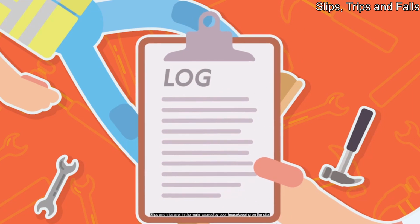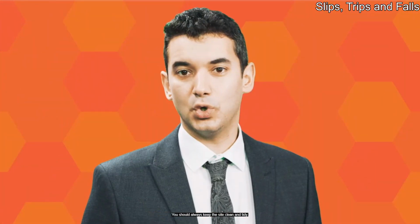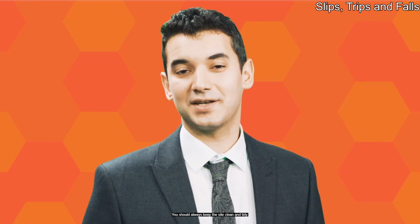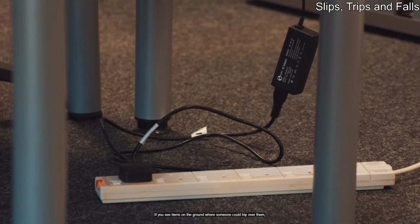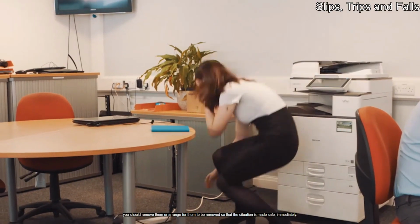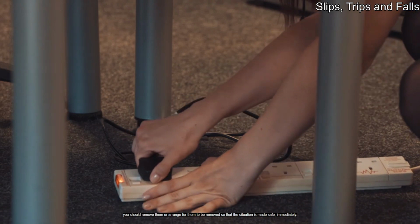Slips and trips are, in the main, caused by poor housekeeping on the site. You should always keep the site clean and tidy. If you see items on the ground where someone could trip over them, you should remove them or arrange for them to be removed so that the situation is made safe immediately.